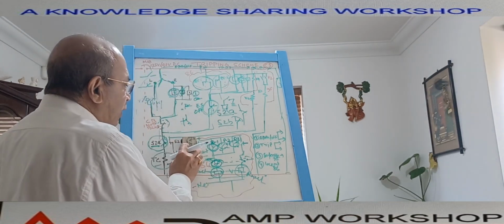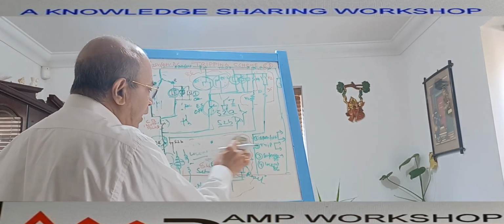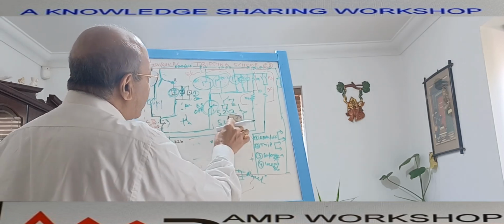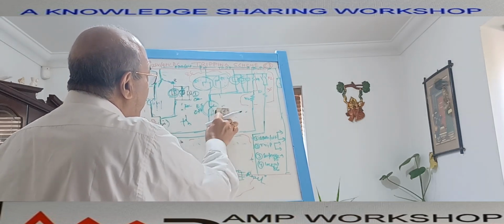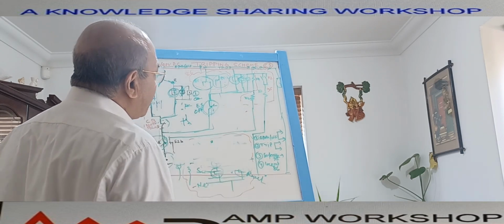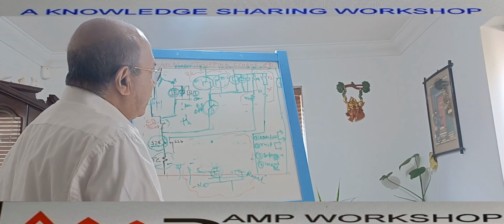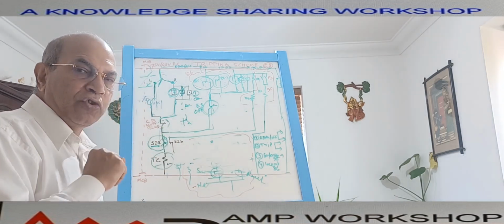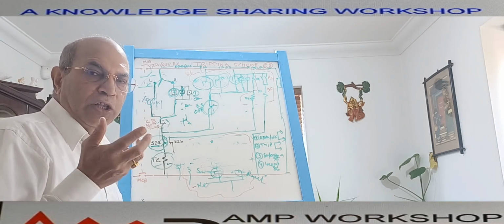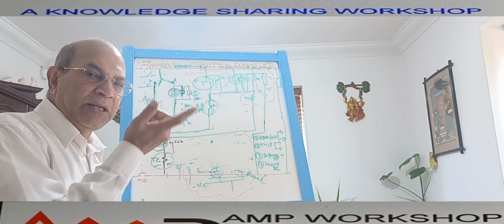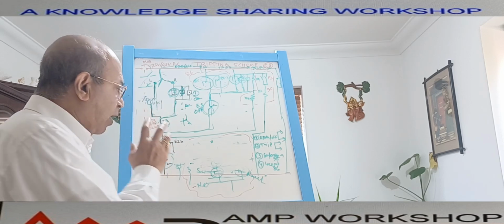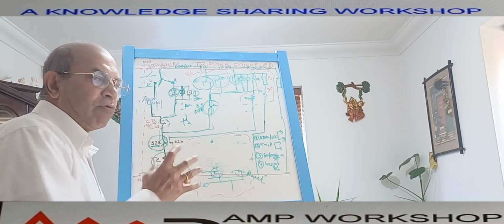Okay, let us remove this part so that it will be more clear to us. So how are we doing this? Suppose we remove this part as well. You see here, there is a relay we already discussed during the circuit breaker closing schematics. The trip coil supervision relay interlock has been inserted in the closing circuit, because if this trip coil has a fault, you cannot close the breaker.